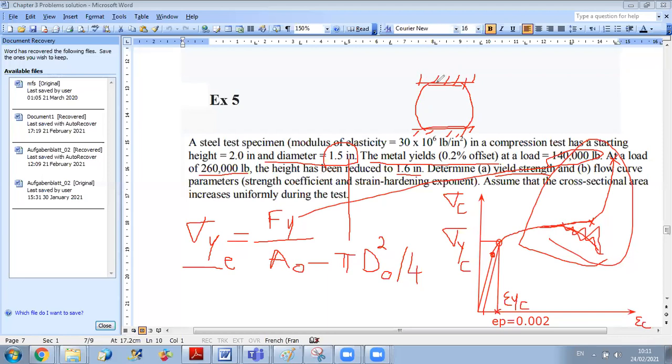It's like the plates are welded to the specimen, or nearly so. And they will oppose any increase in cross-sectional area at this level due to friction between the specimen and the plate, which will create a resistance force. So the more you compress, the higher the resistance force to the increase of this cross-sectional area, and the higher the load F needed to continue your compression.